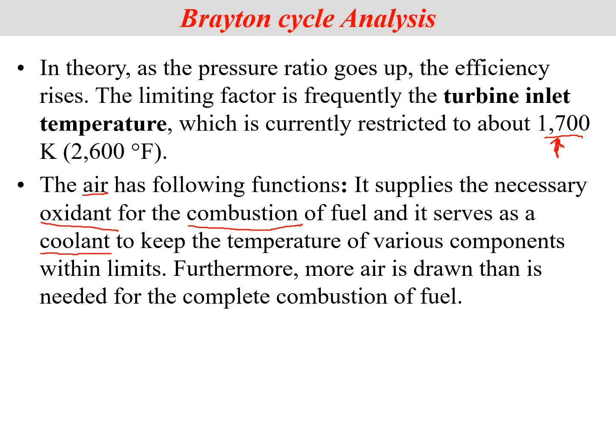You generally don't go very lean, especially in the spark ignition engines, but in gas turbines, you do keep the air-fuel ratio very lean because you also want to take this air in as a coolant. When you are at 20-30,000 feet height, you're not exchanging heat in a conventional manner. You just want fresh air to come in, cool the systems down to a reasonable limit, and then take that excess heat out of the engine.